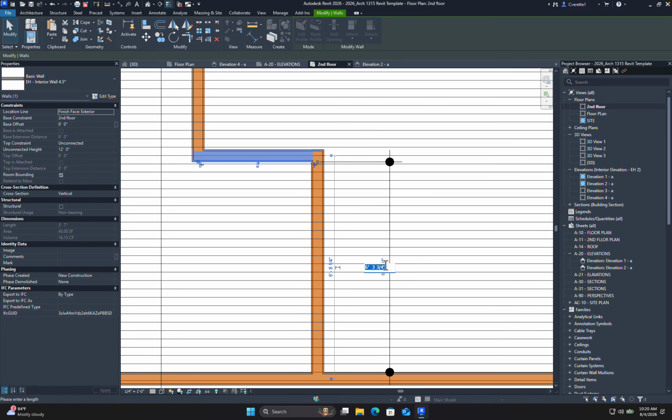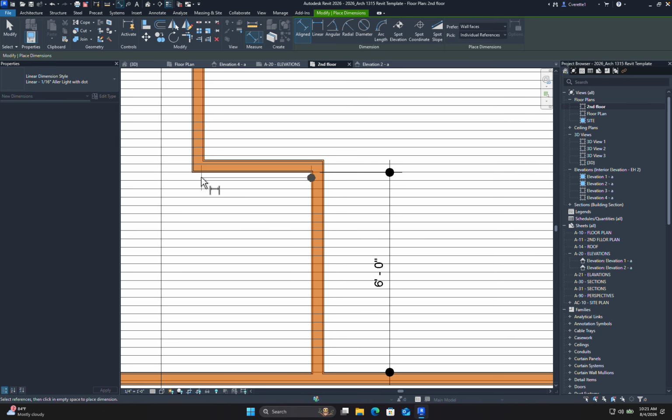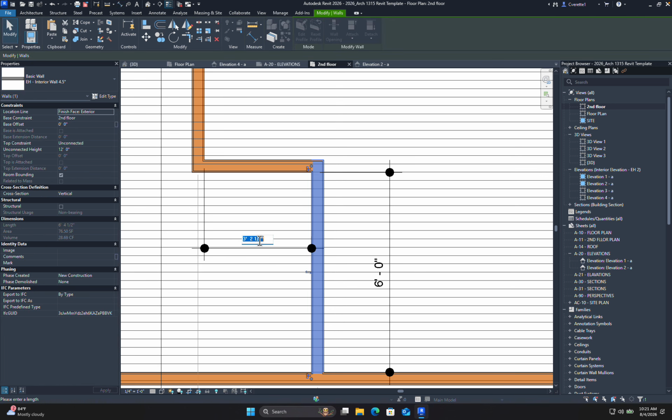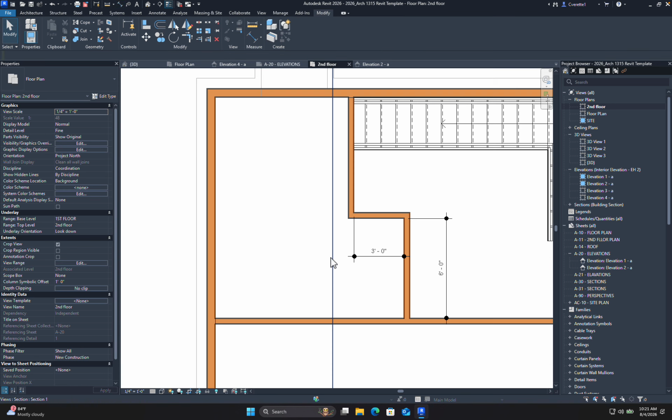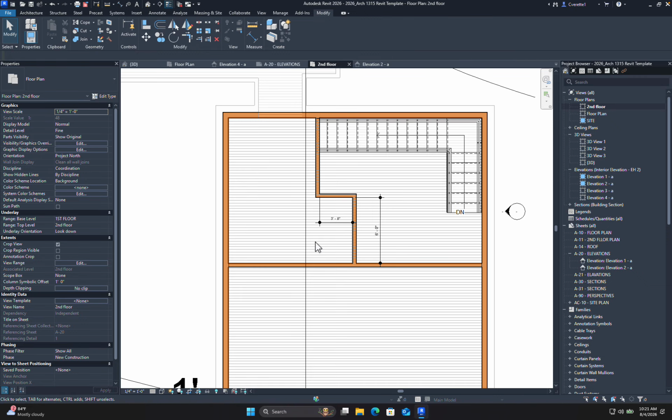However, I could do those automatically. However, I do a lot of high-end residential stuff, and let's face it, their minimums are a little bit different than our minimums, if you will. They can afford them. In our case, their typical minimum is 6 by 3 feet. So in my case, I could set that up, right, by essentially giving myself some dimension lines and, of course, setting those things into place. Don't get me wrong, this is assuming I've already designed this on paper, sketched it out, thought about these things, and I'm simply now taking a sketch and applying them basically to a construction drawing.